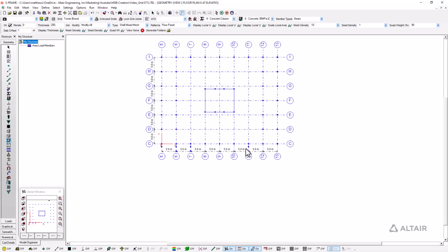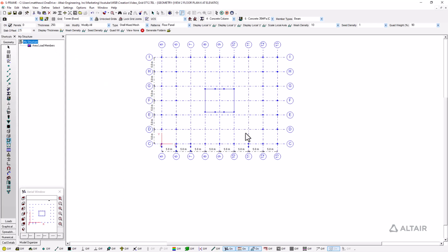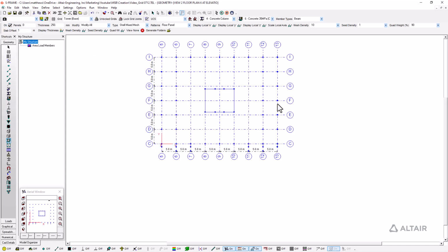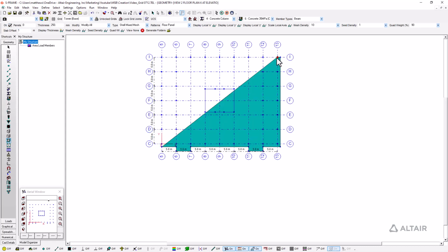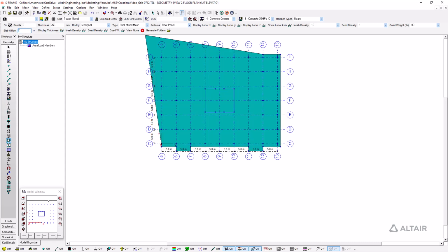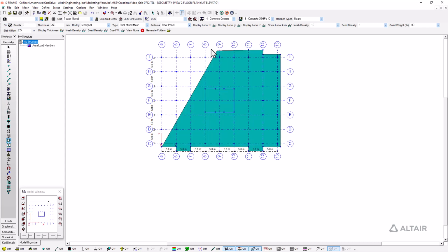So essentially what it's doing is it's allowing us to specify an offset for the next segment of panel that we want to create. So this next segment, again, I want to have a 2.5 meter offset to here, then go back to 1 meter to here, go around the corner, and I'm going to keep that all 1 meter. And notice that it is accommodating that corner and maintaining that 1 meter offset. Do the same thing over here. 2.5 meters for this next segment.